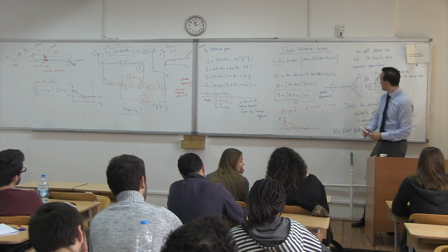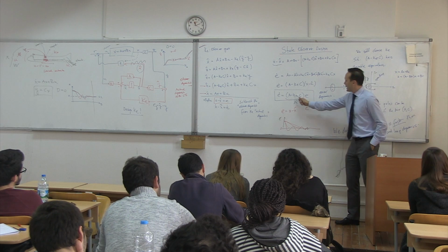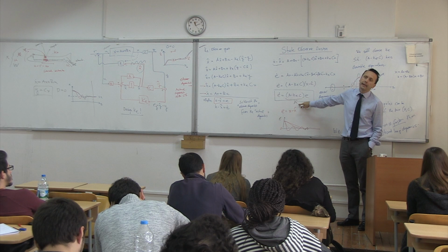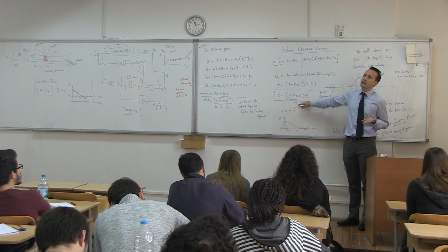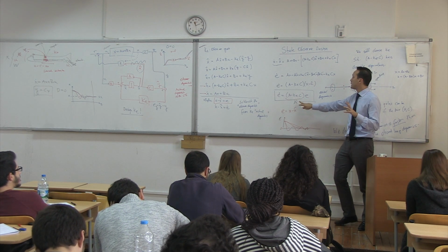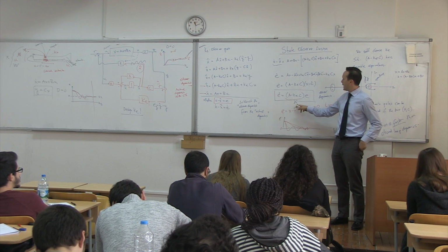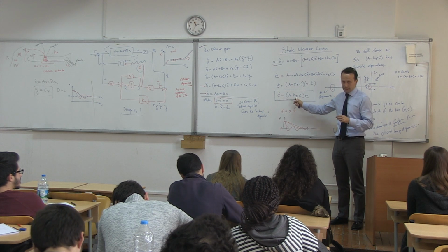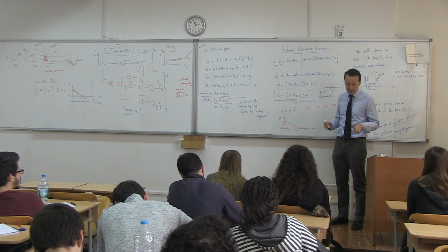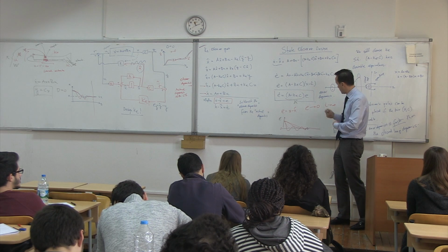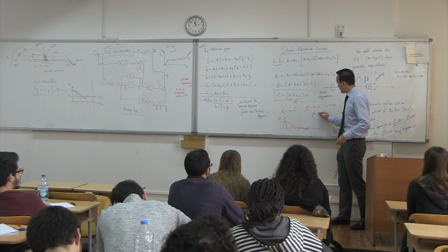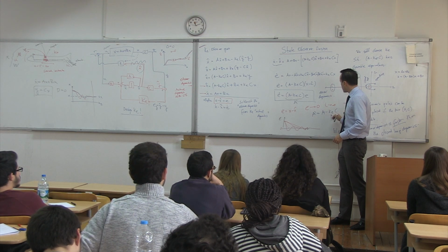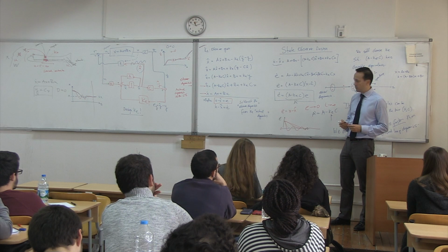All right, so how do I calculate KE? There are lots of ways to do that. Of course, we can assume a desired A prime matrix, and then make this one equal to that, and then make some manipulations and calculate KE. That's quite straightforward. We can simply say A prime is equal to A minus KE times C, and choose KE such that these two match.